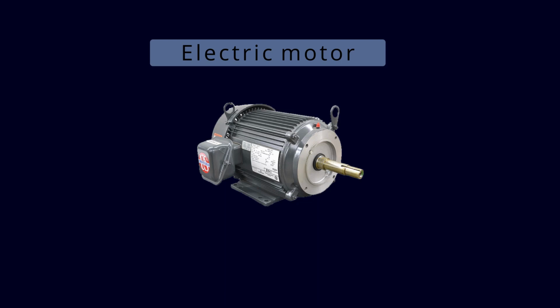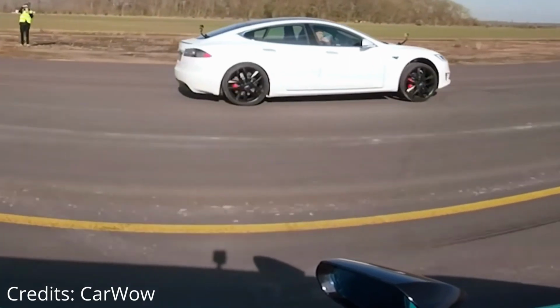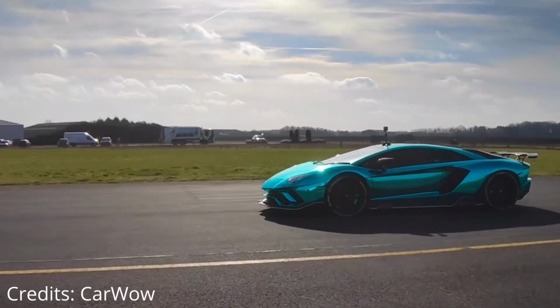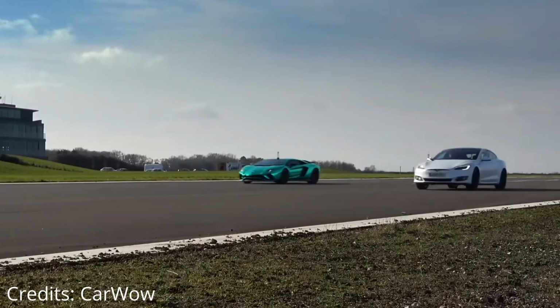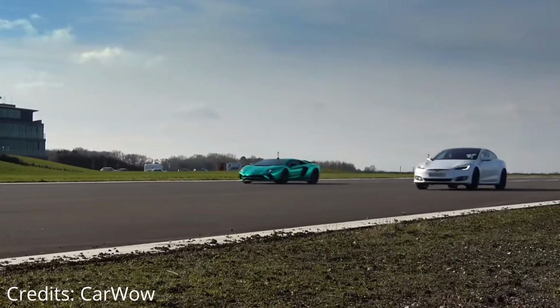To clarify this concept, let's consider two vehicles, one completely electric and the second with an internal combustion engine, both standing still. The first one will have better performance at the start, because in this condition it's very important to deliver all the possible torque in the shortest possible time. And obviously, the electric vehicle will get the maximum torque as soon as the driver pushes the throttle. While the driver in the second car will have to wait for the right RPM range before getting the maximum torque available.